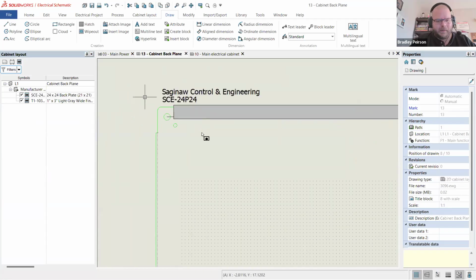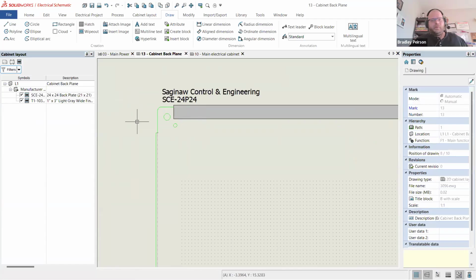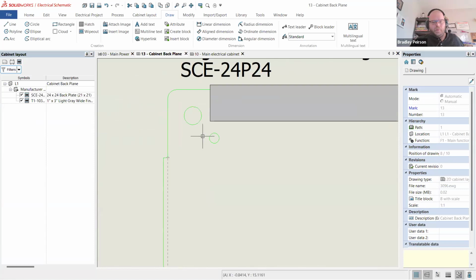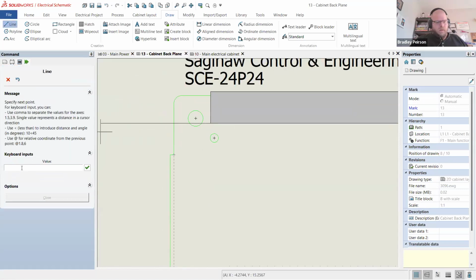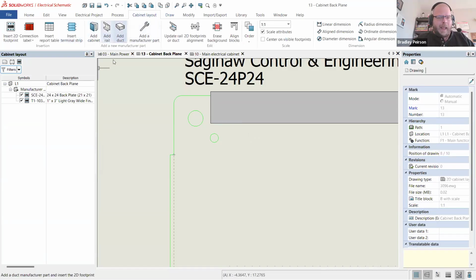And now what I can do is select, just like in SolidWorks, if I drag from the left, I only select the things it touches. So delete those. Those were construction. They don't need to be there. That duct is now in. Now for the vertical run, what I can do is kind of the same thing, a construction line here at 0.50. All right, now it's there. I have a line right there, and that's going to be the starting point of the vertical run of duct.